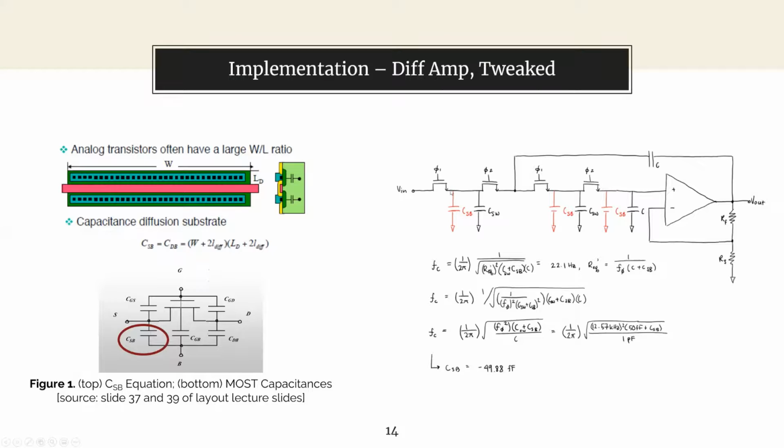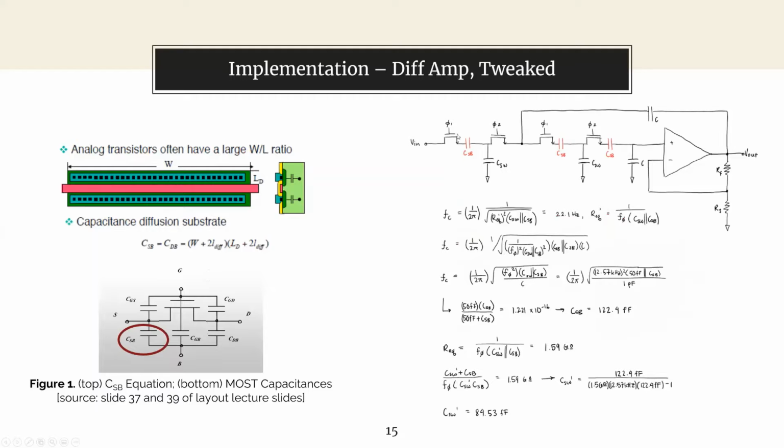which here is modeled as a capacitance from the source of each device to ground in parallel with the existing capacitances. Here I ignored the capacitor associated with this NMOS device just for simplicity, because it is not as easy to model a capacitor with this node. However, this yielded a negative CSB value, so I knew that wasn't correct. So I tried to model them in series as well, coming up with a positive CSB value, which I then used to try to correct the switching capacitance value.